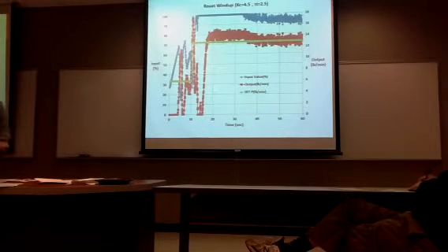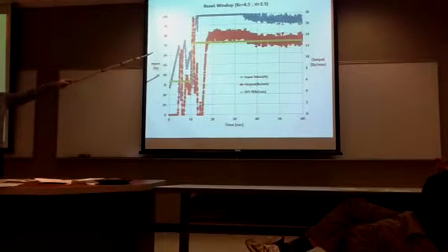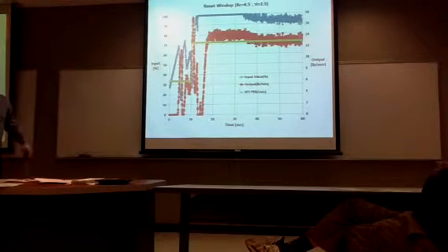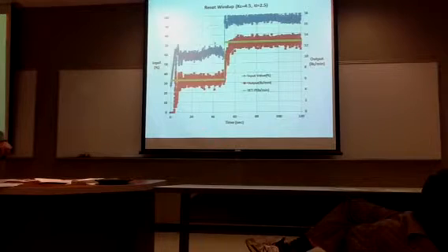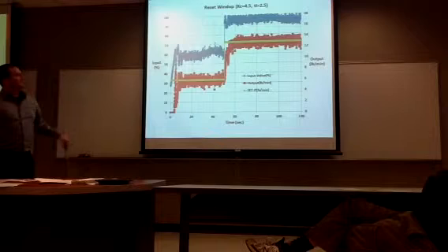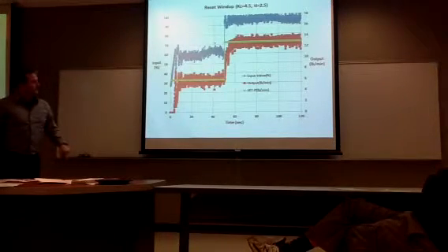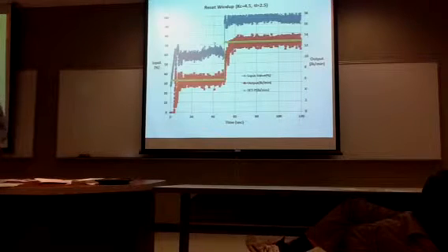I ran the reset windup, and I had the set point change at 10 seconds, and it jumped around and ended up finally settling out after about 40 seconds. But when I ran it again and changed it at 50 seconds, it went almost right in line and jumped right up there in no time. So that was a significant difference.